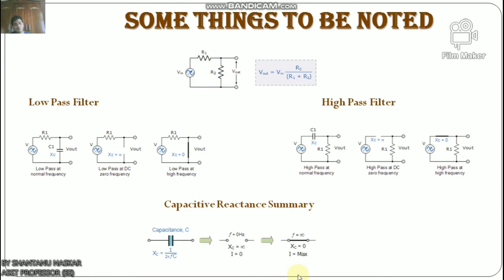Now we know that a capacitor's reactance Xc is actually a complex impedance. The value changes with respect to the applied frequency. If we now change resistor R2 above for a capacitor, the voltage drop across the two components would change as the frequency changes, because the reactance of the capacitor affects its impedance.